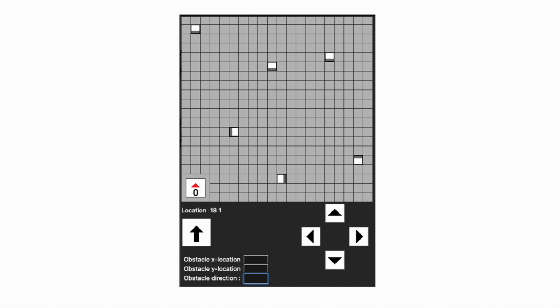To traverse the grid efficiently, we first determine the optimal order of visiting the obstacles. Due to the small number of targets, we can easily test out all possible combinations and calculate which one requires the least distance to be travelled. We can now determine the fastest route to scan all images by finding the shortest path between consecutive pairs of obstacles as determined by the ordering.